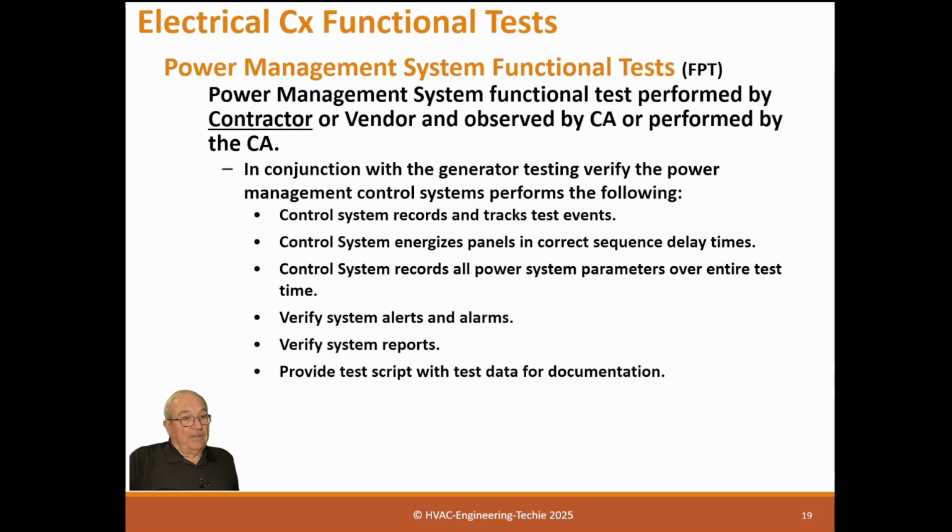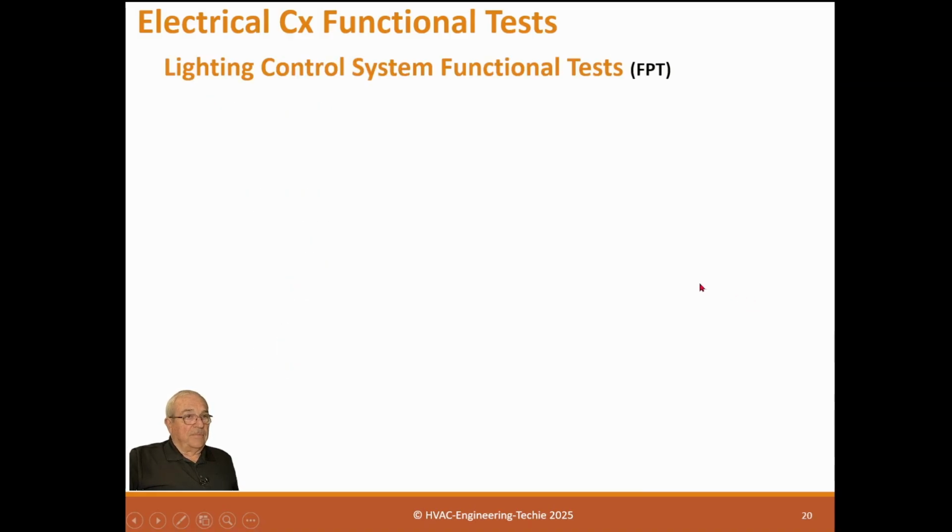When that happened, the generator shut down, the ATS switched over, came back to normal power, and browned out the utility. It was such a big building, and the utility was kind of on the end of their utility feed, so we had to go in and reprogram them all. So it is a problem. The sequence needs to be verified going on and going off, both ways.